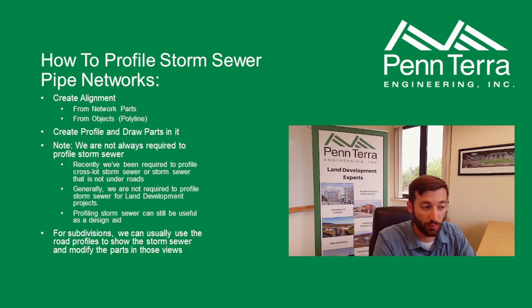Generally speaking, we don't profile the storm sewer with an alignment over the storm sewer. Although recently we have been asked to profile cross-lot storm sewer or anything that's not under roads, which would have their own profiles. For land development projects, we usually do not profile any storm sewer unless we're specifically asked to via a review comment. We do normally show all the storm sewer when we profile a road in a subdivision.